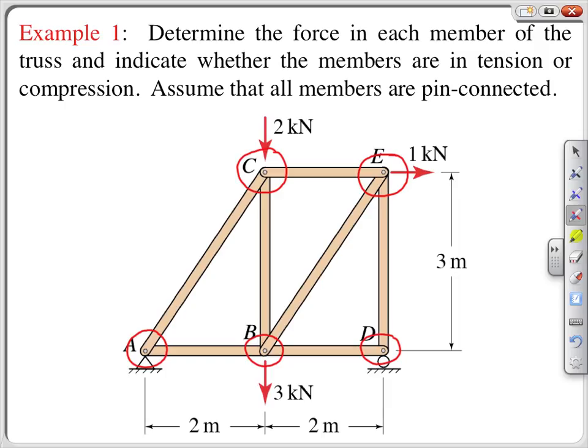Two things to note here: if we're isolating a joint that also coincides with a support, as at A or D, then the support reactions are also applied to those joints. Second, it usually isn't obvious by inspection whether a member is in tension or compression. Although your physical intuition may grow as you solve an increasing number of problems, as a novice, you're probably not going to be able to tell what is in compression and what is in tension, and that's okay.